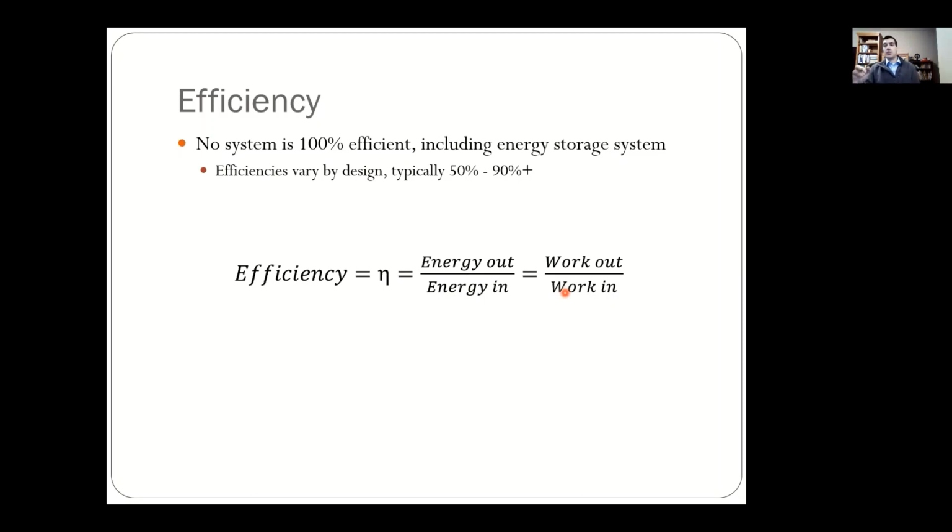All right. And once again, you need to divide this up into charging efficiency and then discharging efficiency. So if you want to talk about the round trip efficiency, the round trip efficiency is equal to the charging efficiency times the discharging efficiency. So let's say hypothetically, this is not realistic, you had a system that was 90% efficient at charging and 90% efficient at discharging. I've got my calculator right here. If I take 0.9 times 0.9, that gives me 0.81.